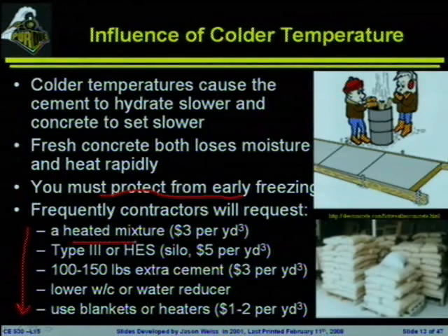A heated mixture, this is something that's fairly common in the Lafayette area here. You'll notice if you drive by 65 at various times during the year, you will notice that there is heat coming out of the aggregate bins. They're actually going to heat up the rocks before they place them into the back of the truck. They'll heat up the water, and that'll cause the concrete to be a little bit warmer when it's placed.